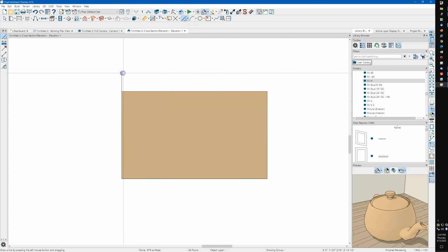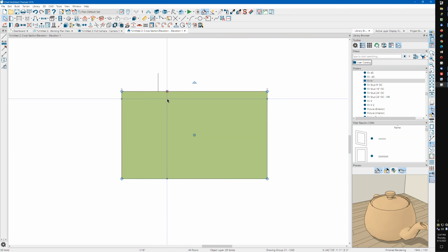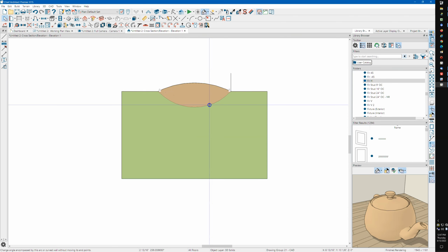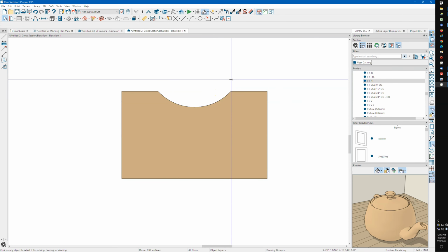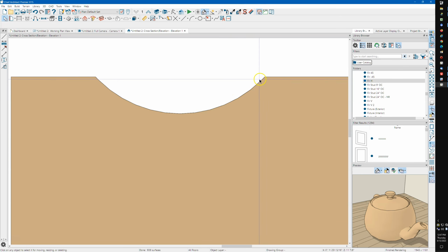And I'm going to pick up a snap here. Let's drag this over 5 inches. That's just a completely arbitrary amount. The only thing I'm going to use that for is to put a snap right there. I'm going to take this, reflect about the center of that, put another break right there, and then while that's selected, I'm going to change that, put a curve there. I can delete that line, and if you zoom in here, you'll notice how that's kind of faceted.